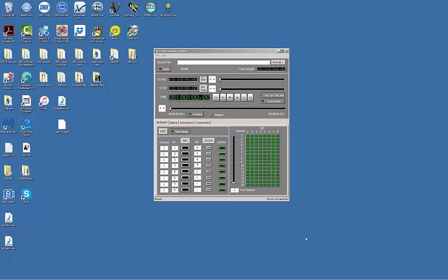without a sound source. It also is used for programming dynamic lighting, including dimmer packs, multicolor lighting, and motion control lights. The other purpose for this program is to provide a system test tool. It can check out your system's network connectivity. It can provide remote centralized control of the devices in the network. This includes playing back audio, DMX launching, checking input triggers, and also debugging sequences used by the Minisam and the